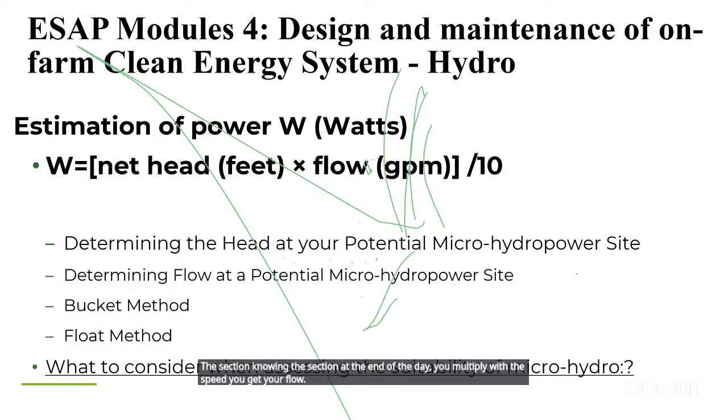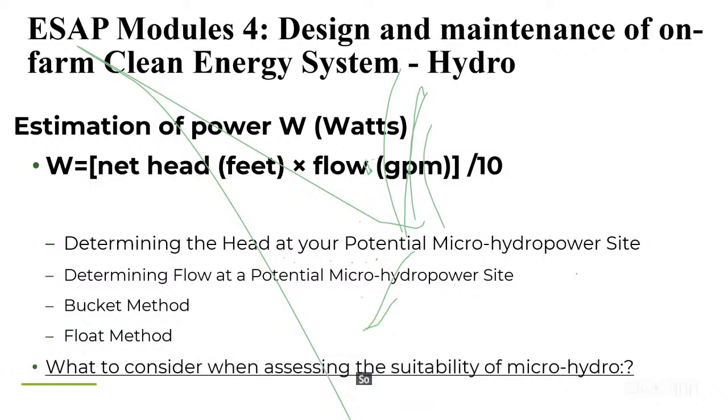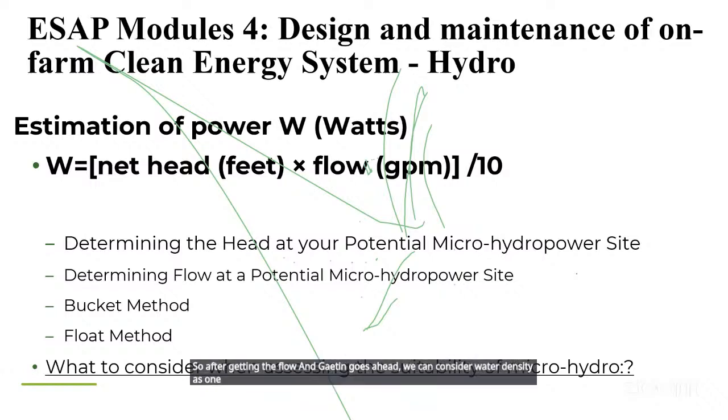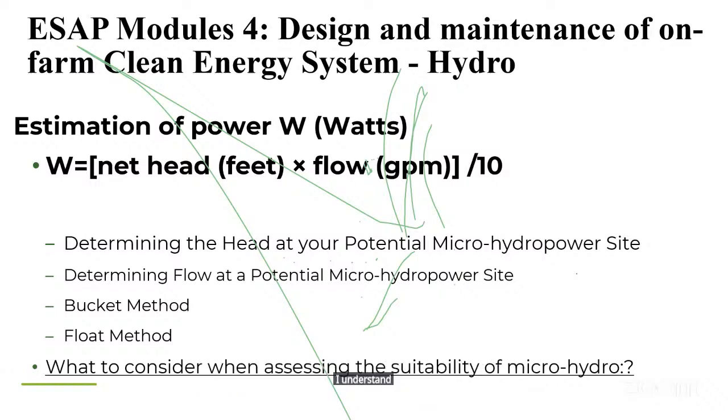flow. So after getting the flow and getting the head, we can consider water density as 1, and you compute the power estimated times 10, and you multiply by the time, you have the energy.